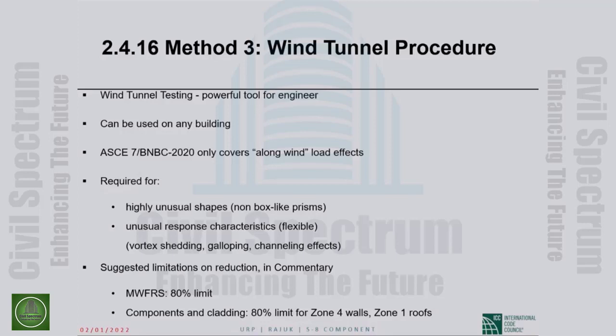Unusual response characteristics, that would be the case with highly flexible buildings. Then we should not try to use the analytical procedure. And then all the across wind phenomena, vortex shedding, galloping, if you want to capture those, then you need wind tunnel testing.